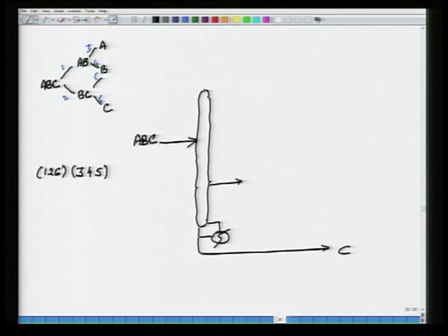And then this is section 1. From the top of section 1, which is a rectifier, I will take a vapor stream. That vapor stream is AB vapor. This is sent to a rectifying section. This is my rectifying section. The rectifying section has got its condenser. I won't show the reflux drum. Well, let's show it anyway. So, this is your rectifying section, it has got its reflux, and you are taking out pure A up the top.